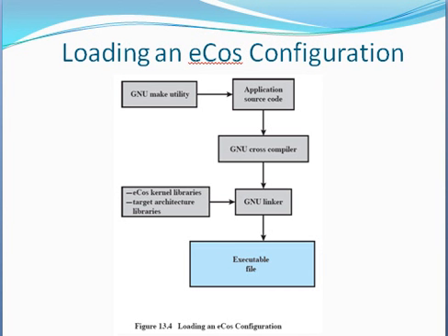There may be only one version of the application source code, or there may be variations for different versions of the target embedded platform. In this example, the GNU Make utility is used to selectively determine which pieces of program need to be compiled or recompiled, and issues the commands to recompile them.